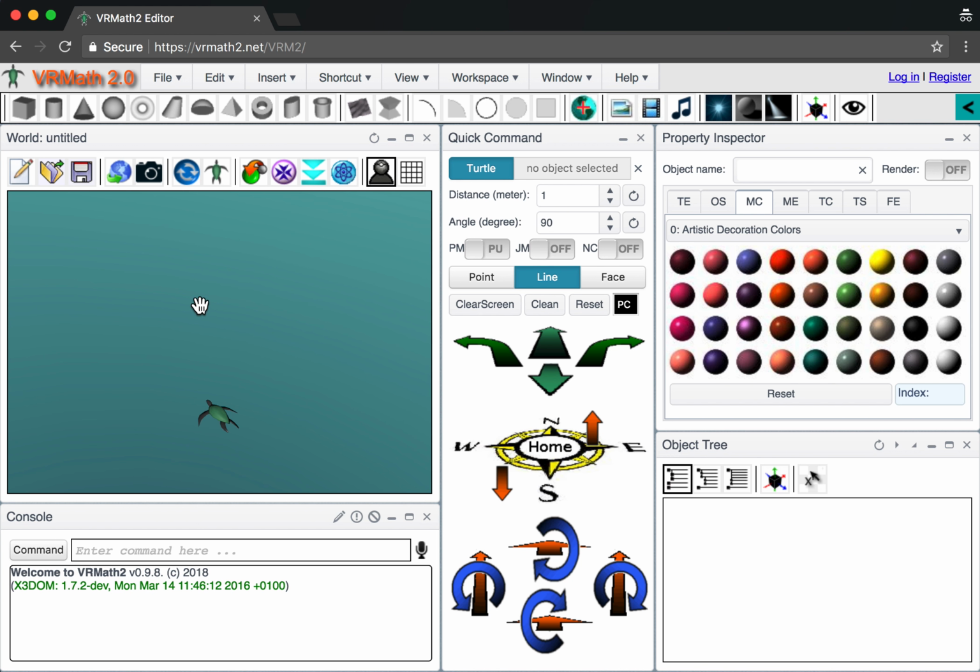There are quite a few important things here in the 3D window, because we need to navigate. To navigate in the 3D space is pretty important, and by default the navigation mode is called examine. Examine is kind of drag to rotate the world. So you need to imagine that you are actually spinning the world around, or on the other hand, you may imagine that you are actually going around the world quickly.